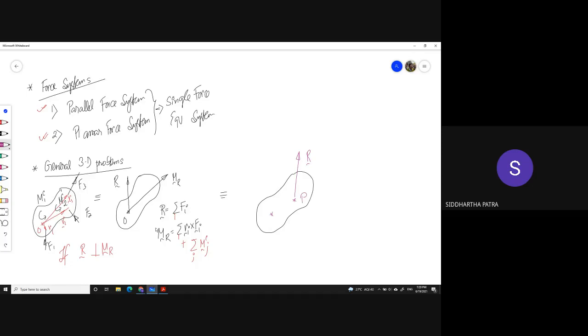Okay, this entire moment MR, as we discussed, is the sum of multiple couple moments. So these are individual couple moments, and these are also certain couple moments. Now these couple moments came from the original system as it is, and this came here because forces from each location were shifted to O. But if I shift all the forces to P, then the resultant is the same expression, and I would not need any moment correction.